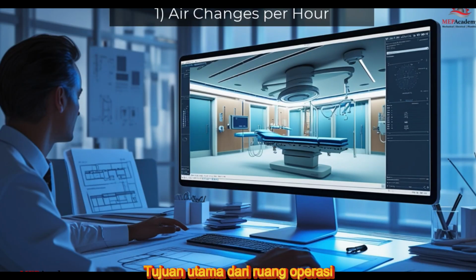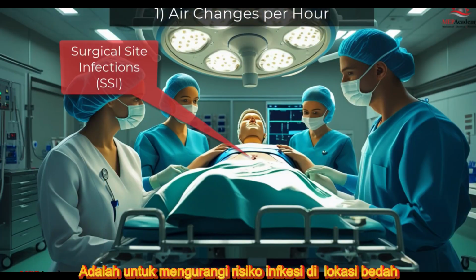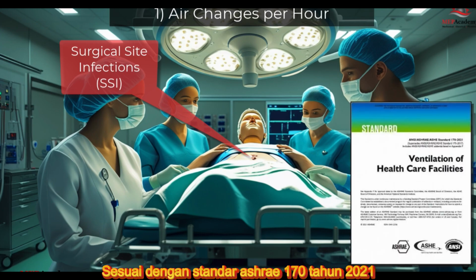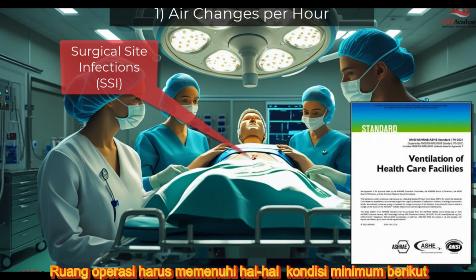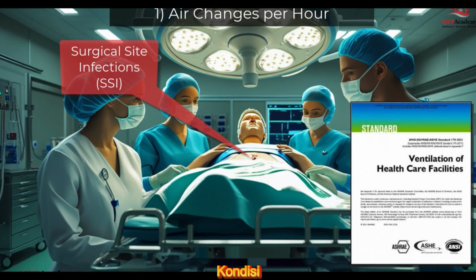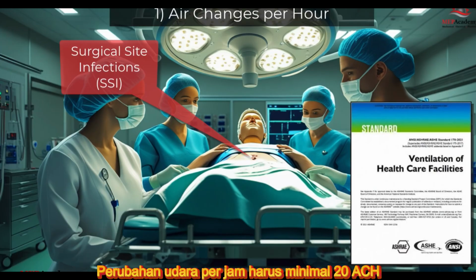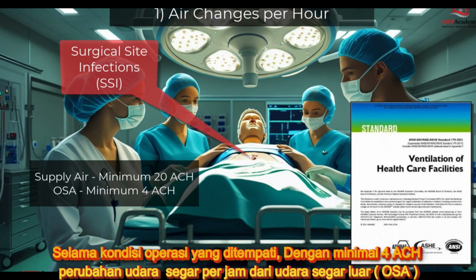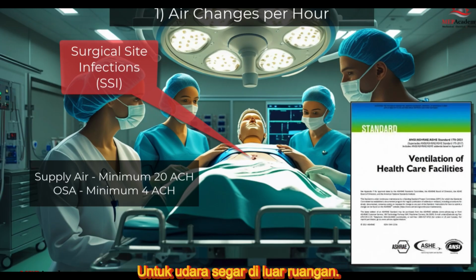The primary purpose of an operating room HVAC system is to reduce the risk of surgical site infections, SSIs, by controlling airborne contaminants and maintaining a clean, stable environment. According to ASHRAE Standard 170/2021, an operating room must meet the following minimum conditions. Air changes per hour shall be a minimum 20 during occupied, surgical conditions, with a minimum of 4 air changes per hour for outdoor, fresh air.